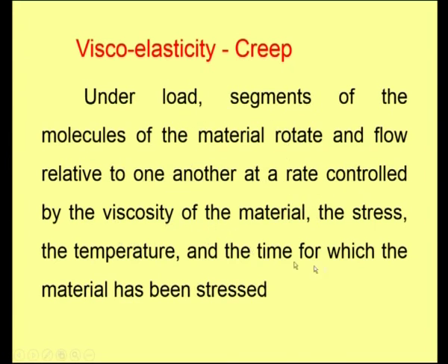Apart from the viscosity, the magnitude of the applied stress and then the temperature, of course earlier we have seen temperature has a great effect on viscosity. Higher the temperature, the viscosity is less. And then particularly with respect to viscoelasticity for polymers, given sufficient time, the material will relax. So the time for which the material has been stressed. These are the factors that will control the creep experiment.